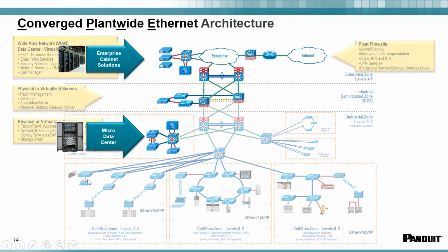And at the same layer, you find something called industrial distribution frames. This is where you're segregating the communication, where you are making sure to separate the copper from the fiber. So within the control system and automation system, you most likely are running copper wires to all of these devices.